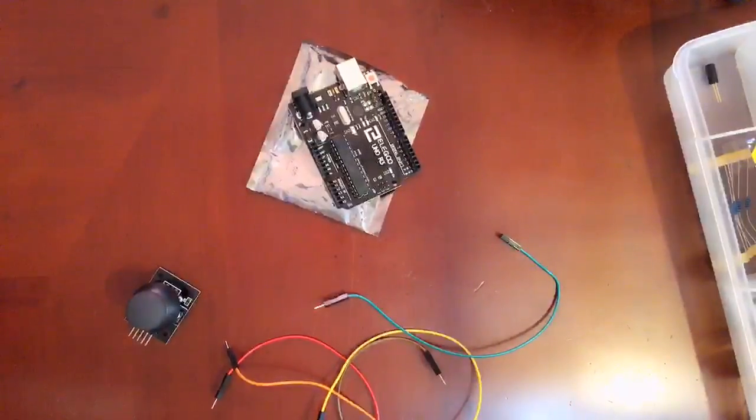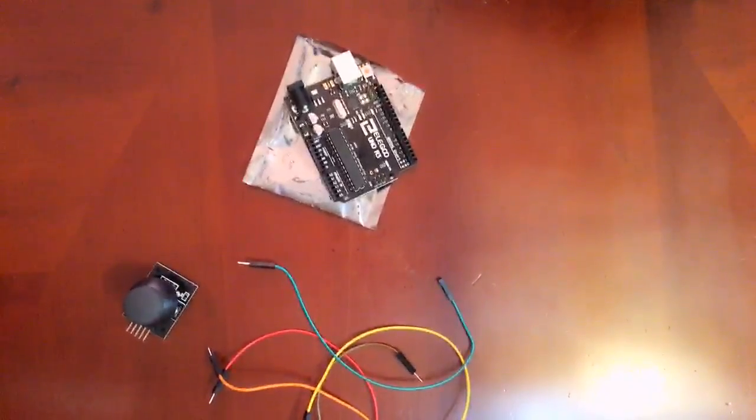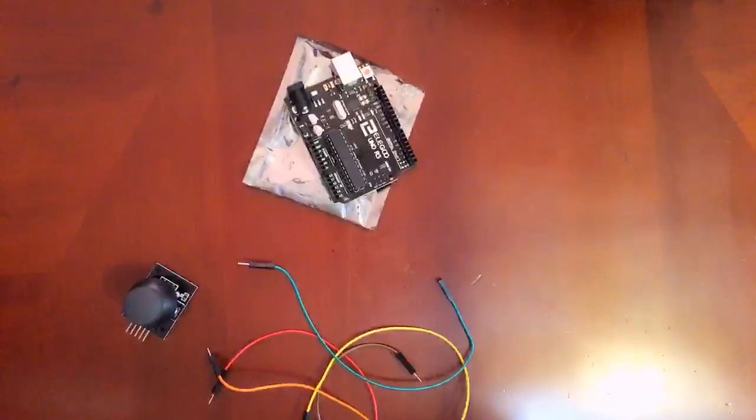Okay. We have to use analog Arduino pins to read the data from the XY pins, and a digital pin to read the button. The key pin is connected to ground when the joystick is pressed down and is floating otherwise. To get stable readings from the key select pin, it needs to be connected to VCC via a pull-up resistor. The built-in resistors on the Arduino digital pins can be used. For a tutorial on how to activate the pull-up resistors for Arduino pins configured as inputs. Okay.